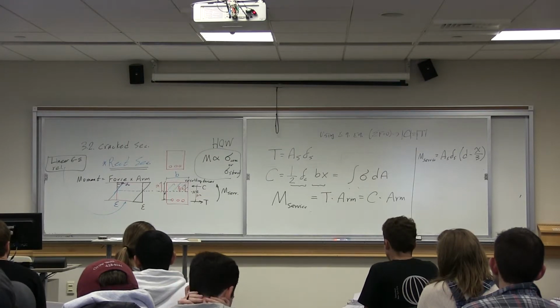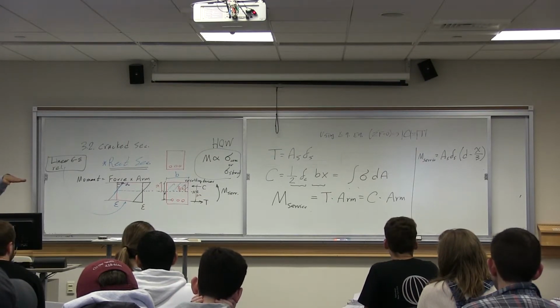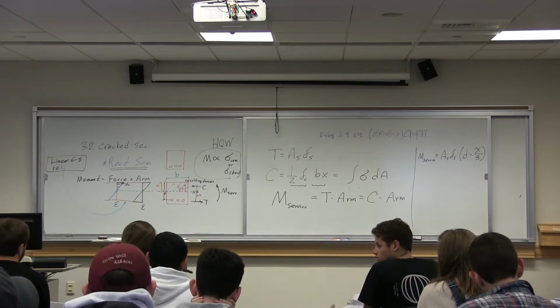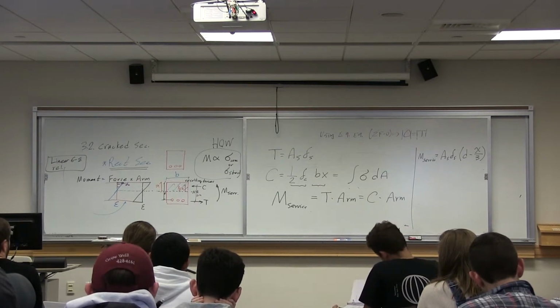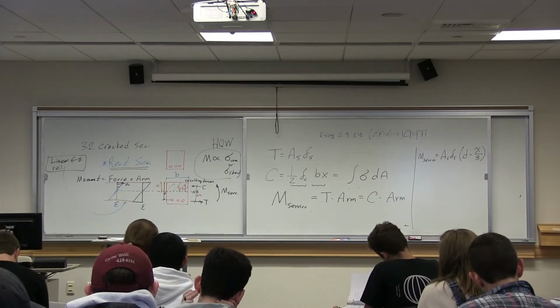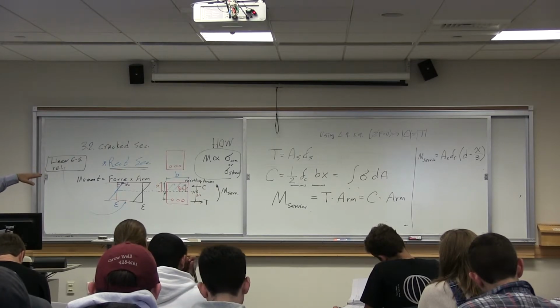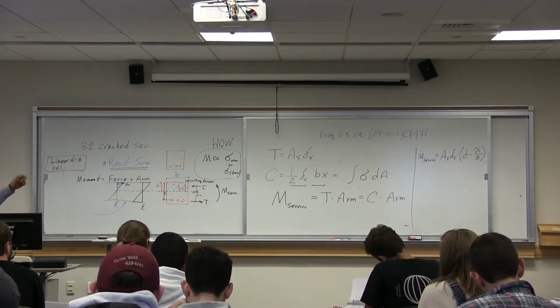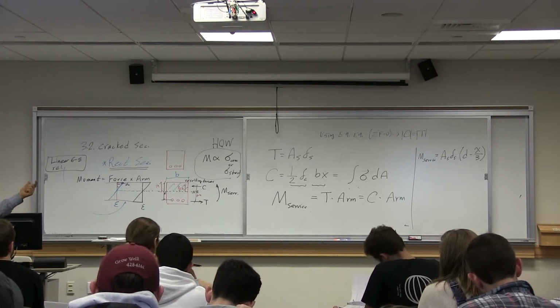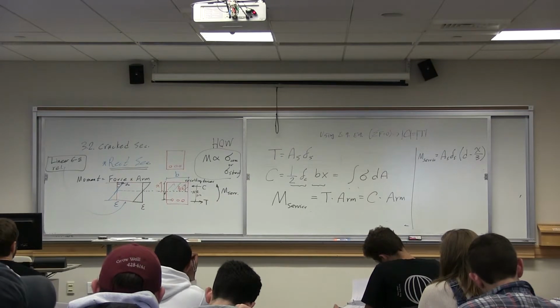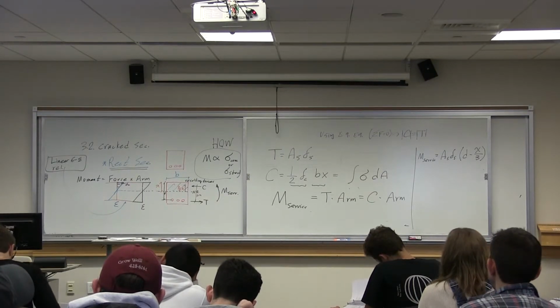With section analysis, you find the centroid of the section, you find X, or with that simple relationship you have for k. We know how k is related to n and rho. You use that relationship, find k, from k you find X, you plug in here, and you have a relationship between M and Fs. If M is given to you, you find Fs. If Fs is given to you, you find the moment.